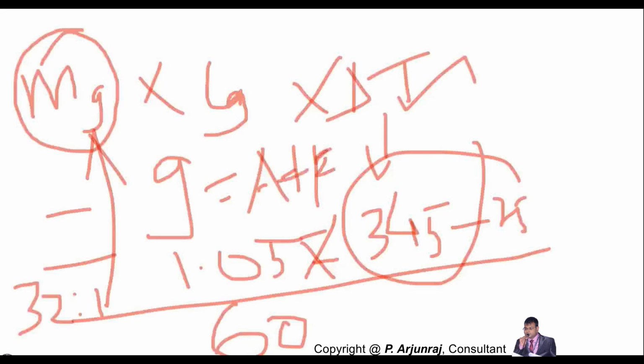So when you add the air along with the fuel, you get the mass flow rate of the gas, which is nothing but 33, not percentage, it's 33. Hope you agree with this. And again, here they have also given in the problem 2.5 as the mass flow rate of the fuel.